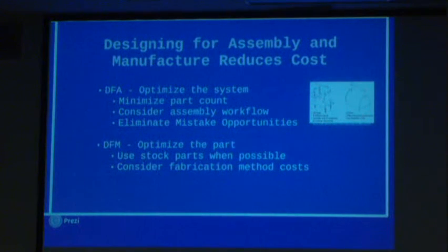So if you think about this assembly with the handle, that little slot where the cross pin went was on one side. And I created that little chamfer to show you which end it goes in. So you had a lead in, it was easier to put in, and you had a visual cue as to which side to put it in. Because if you inserted it the other way and you went to put your cross pin in, it wouldn't be located properly, right? So you got to think about those kind of things in assembly.